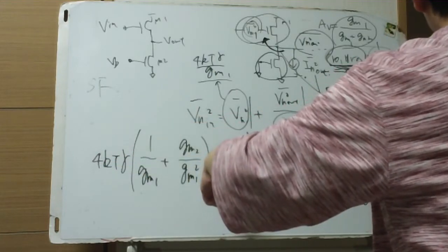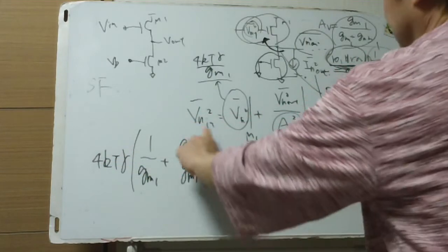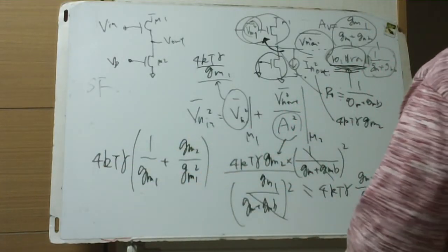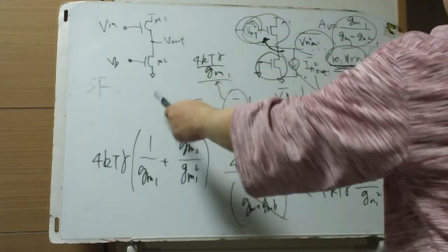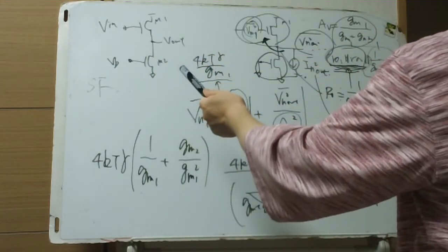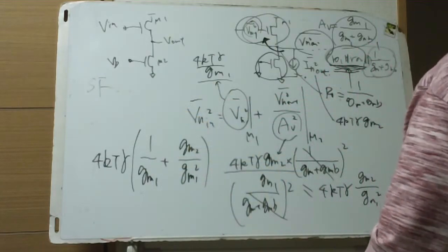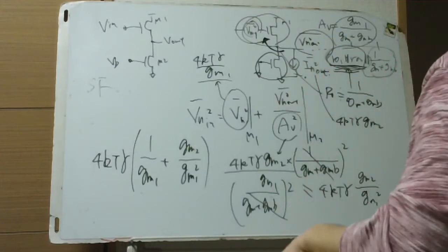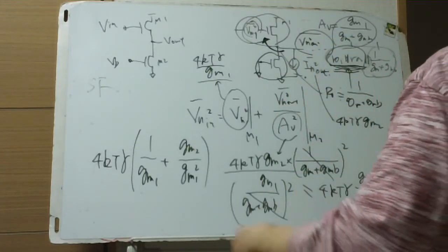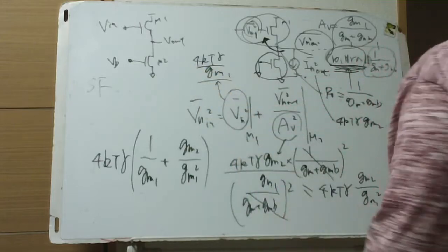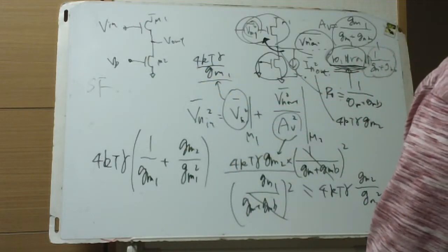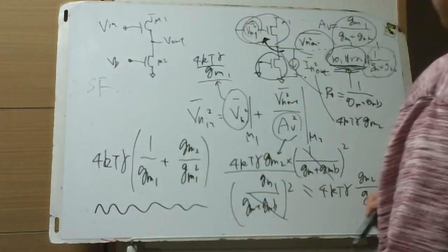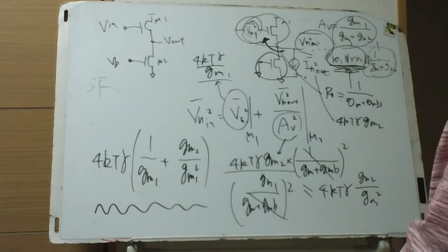Even if the input referred noise is calculated at the same level, with the same geometry of common source amplifier and source follower compared, the source follower has very small noise. So we use this type for low noise amplifiers. So finally we got there.